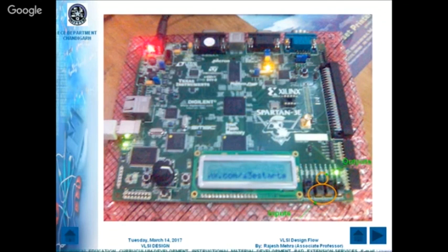You need one output for sum, another for carry. For providing actual input from physical devices, we are using toggle switches here. So two toggle switches are used to provide 0 and 1. And by providing this 0 and 1, you have to check sum and carry. So we are using two outputs in the form of LEDs. We check the transition of those LEDs, whether it is on or off. So as you can see, it is on. So in this way, after the bit file transfer, you can check your design in hardware by making transitions over the toggle switches, and you can monitor the outputs in the form of zeros and ones.